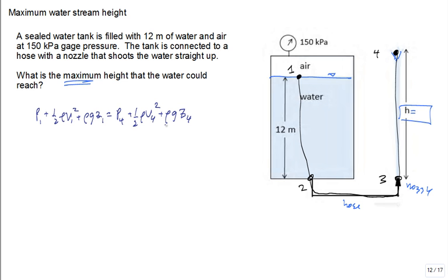Did I apply Bernoulli's along that streamline? I know there's some assumptions. It's inviscid. Good luck. Right? But this is a maximum height. When I account for some viscous effects, it'll reduce that maximum height. The actual height will be less.